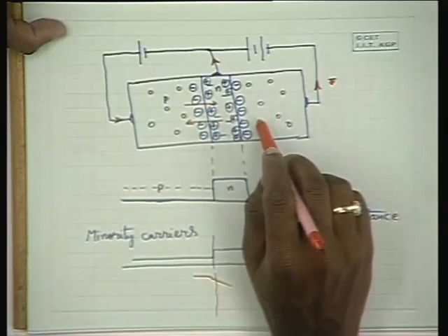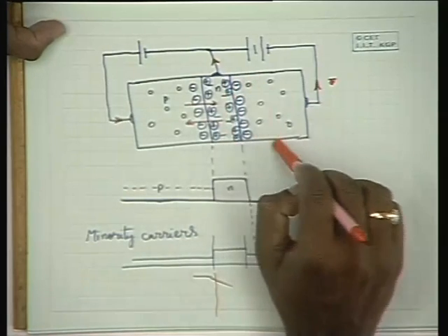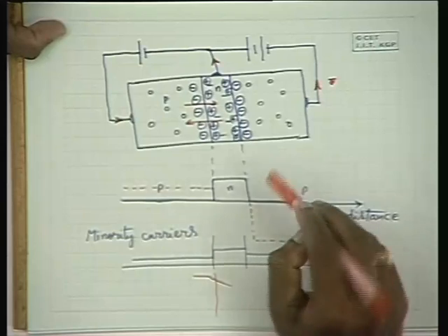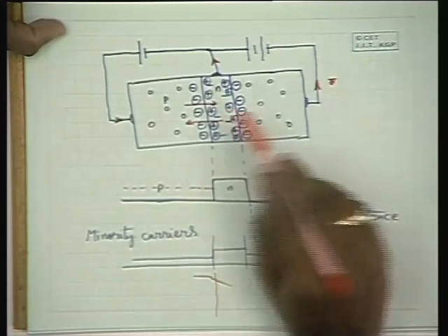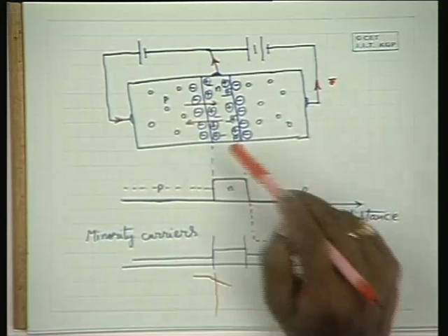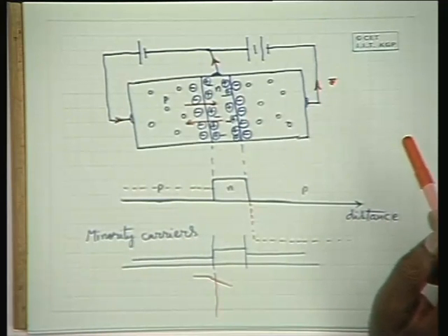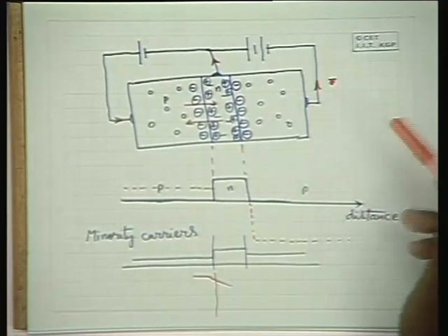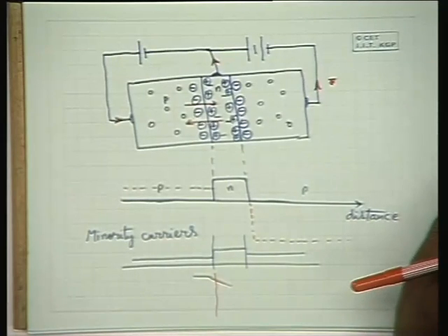So when the doping concentration is low, the depletion region would be large and the potential difference would be large, and the transportation of the injected charge carriers into the collector would be better, because that is desirable for operating this device as an amplifier. We shall discuss about it subsequently. It's clear? Any other question?